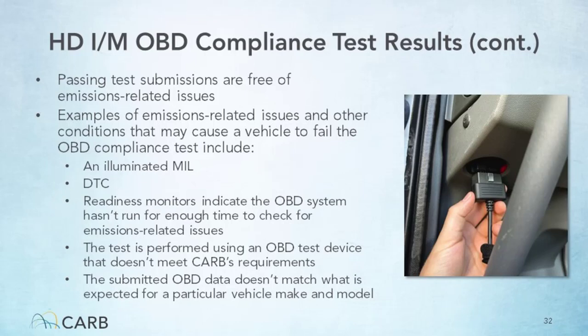It is considered bad practice to clear diagnostic trouble codes, or DTCs, shortly before performing the Clean Truck Check emissions test. Clearing DTCs will also reset readiness monitors within the OBD system. To properly assess the vehicle's emissions systems and determine vehicle compliance with Clean Truck Check, certain readiness monitor checks will need to be completed.